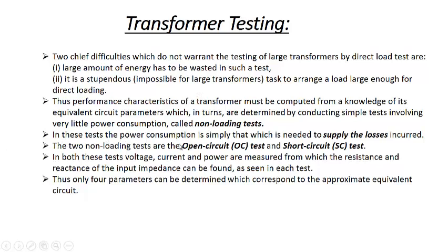In these tests, the power consumption is simply what is needed to supply the losses only. So there will be power loss in doing such tests, but it will be only minimum. They will be only these losses. So the two non-loading tests are the open circuit test and the short circuit test.